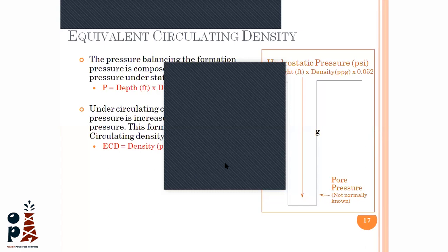So TVD is not measured by anyone. It is just sensors, and we use the drilling line to help calculate this TVD. The measured depth is the length of the connections itself. Oh, I'm sorry guys, he asked about the TVD. Yes, it is used, it's calculated by the MWD using the inclination and azimuth data. So we get it from the MWD guys. I was just confused. The TVD is calculated by the MWD tools.